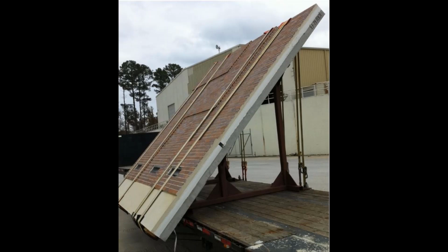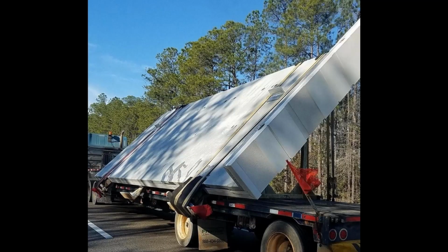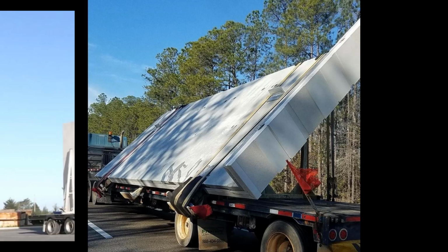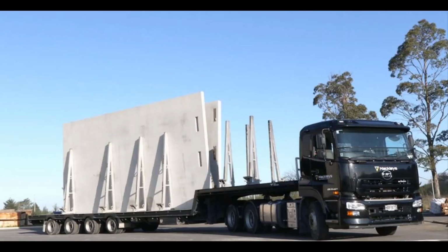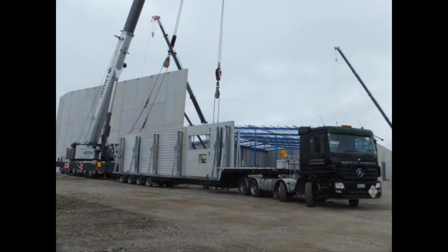For pre-stressed panels, the panel width is limited to the precaster's long line form width, as well as shipping restrictions. Panels more than 12 feet wide may require special handling, and panels wider than 14 feet can be a challenge to ship by road due to the lane width and minimum bridge height along the chosen route. Individual panels are more flexible with possible lengths of 70 feet or more.